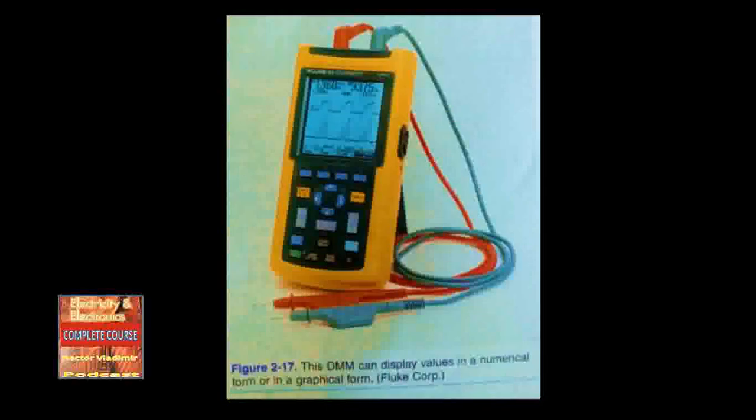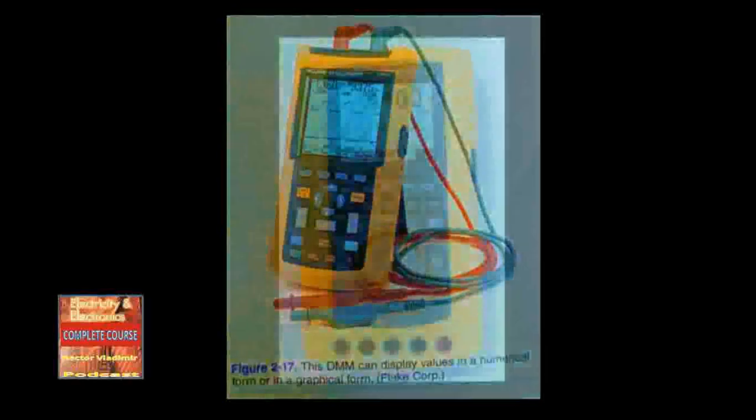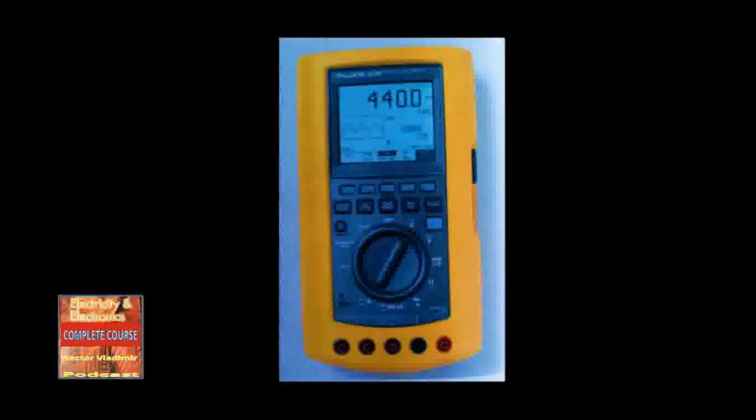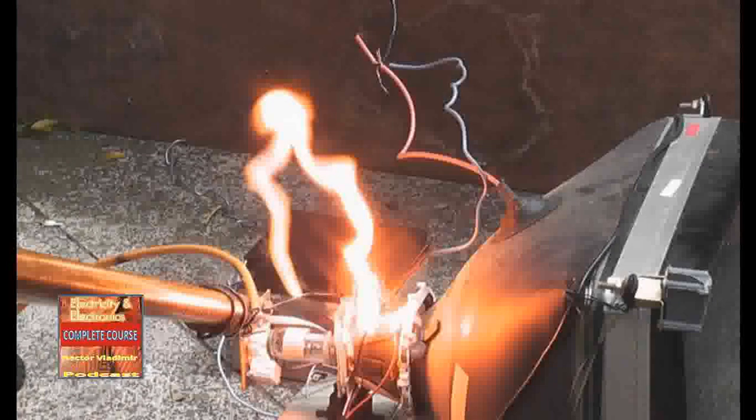Make a habit of testing circuits safely when danger voltages are present. Do not make the common mistake of connecting the meter to a voltage source without first changing the selector mode switch after checking resistance or amperage. In addition, some meters have a separate input for the test leads when in the current mode, especially when high currents are to be measured.